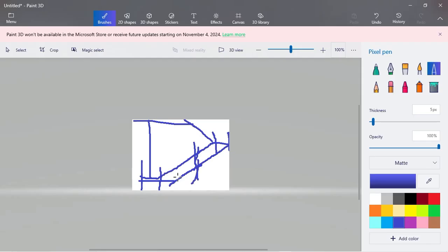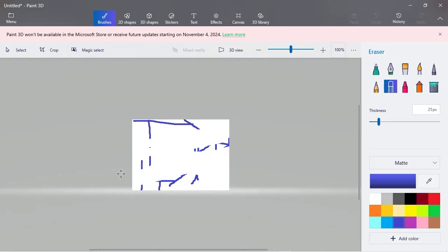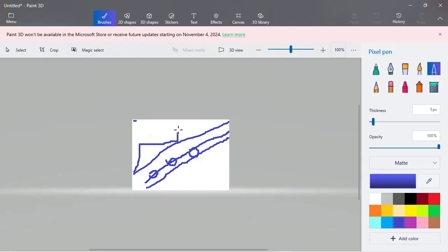As you know, only the rebars are found in the stair thickness, because if we have our stair maybe here, and this is the thickness, and then our rebars can run in this way and also in this way, but not in the risers and the goings.